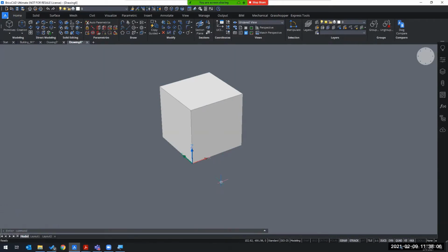And so now let's do some manipulation on the faces. Let's start with just one face. As you can see, my selection mode is on 0. So if I want to select my face, I can either click Control to toggle through the selections, or I can just activate the face. And since we're going to be selecting a few faces, I will leave that option on. So how about we use the push-pull tool to manipulate just this face?